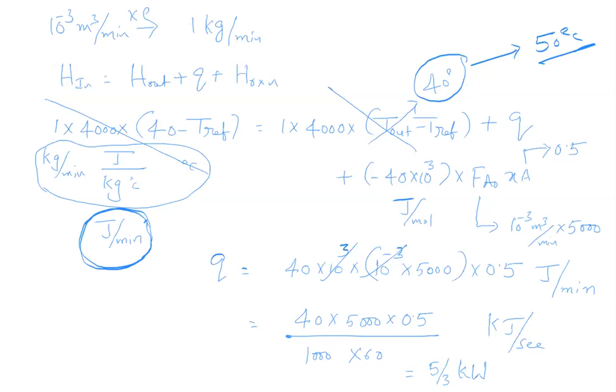We cannot solve without considering T reference because it is technically not right. Because how enthalpy is defined is m Cp delta T. But without considering T reference also we'll get the same answer. But T reference is the technically right way of solving the problem.